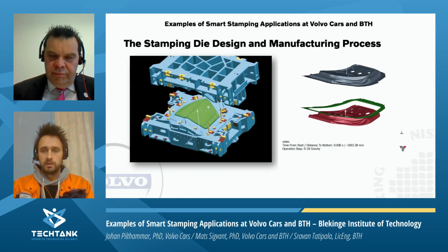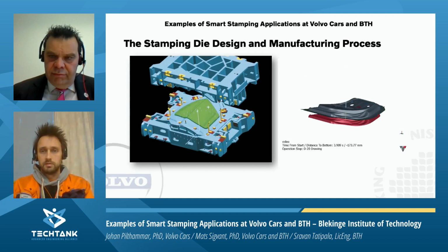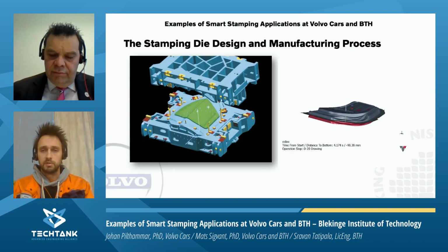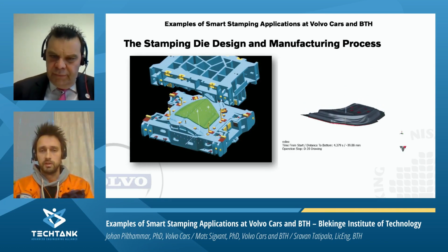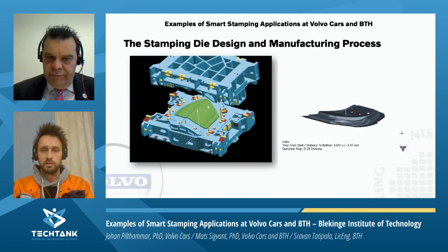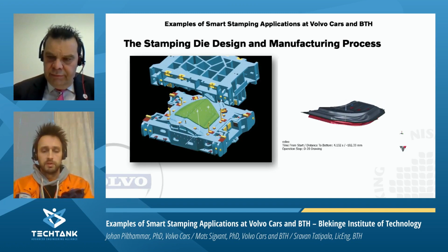So to the right here, you can see how the traditional way is to conduct a sheet metal forming simulation. You can see the parts moving around here are the only parts of the stamping die and the press that are in the simulations today. So we are disregarding all of the structures in the stamping die and all of the flexibility and tilting and so on in the press machine. So we have the forming surface of the matrix, of the punch and the blank holder. But we are skipping that they themselves are bending.